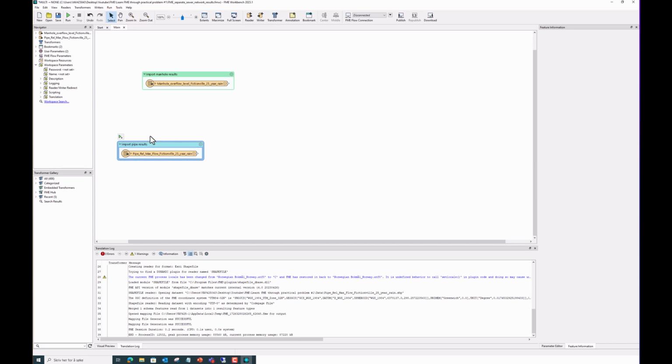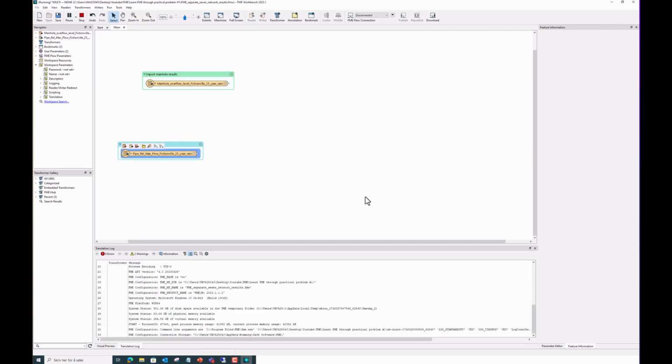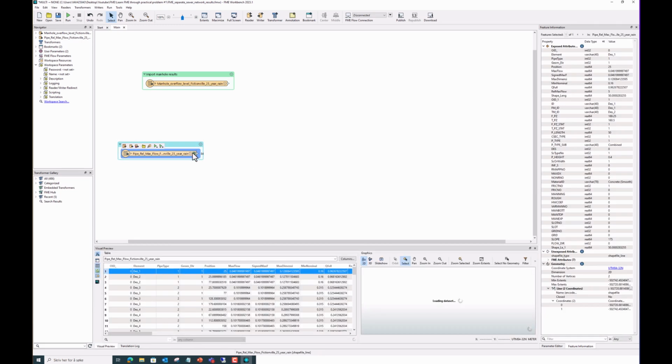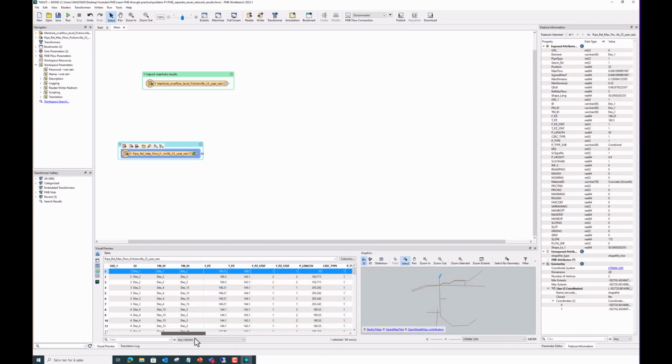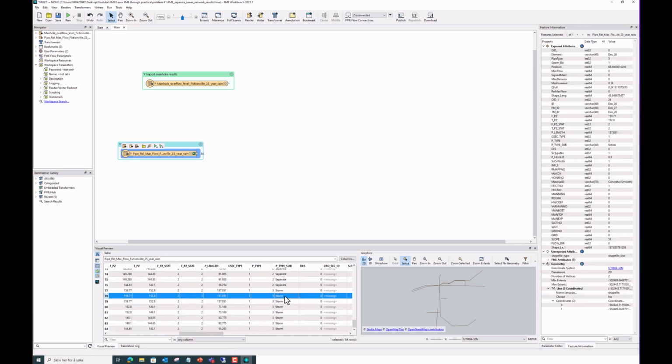Import pipe results. So as I mentioned before, if I run the data for the pipes and inspect the data, we see that there is an attribute that is called, in this case, p-type sub, and it says whether it is combined, separate, or, there aren't too many stormwater pipes, but here, if it's a stormwater pipe.